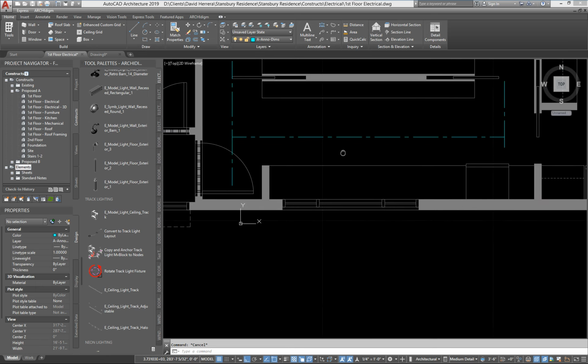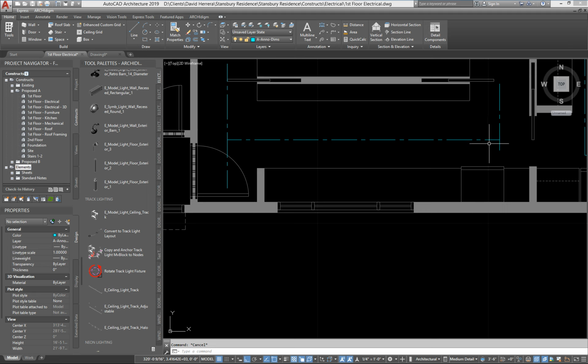Let's take a look at this area first. This is a very simple scenario where you want a set of ceiling cans. So the first thing I'll do is I'll go ahead and convert this line. This is a regular AutoCAD line, and I drew it on a layer where I intend to print that line, and I want it as a center line because I want that to be clear to the contractor that this is the center line of the objects, but it's also what it's centered on. This will be centered on this particular door.